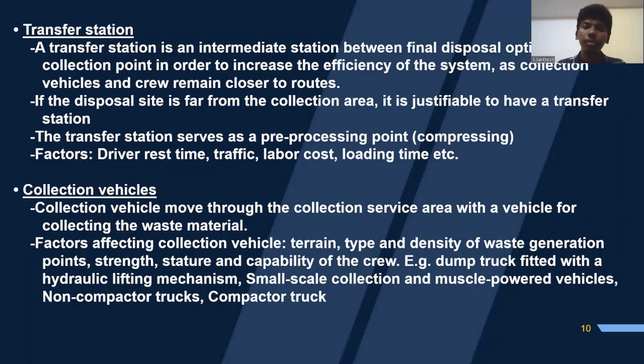A transfer station is an intermediate station between final disposal option and collection point. So after the collection and before the disposal of the waste, you'll have this transportation in between them. So let's see about that. As collection vehicles and crew remain closer to routes, if the disposal site is far from the collection area, it is justifiable to have a transfer station. The transfer station serves as a pre-processing point.